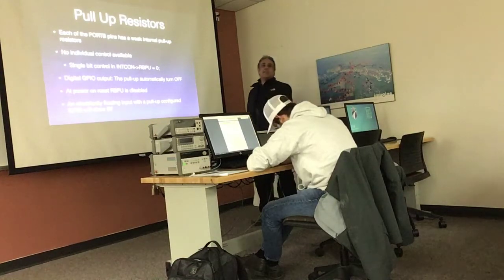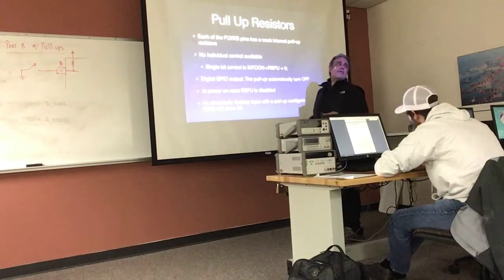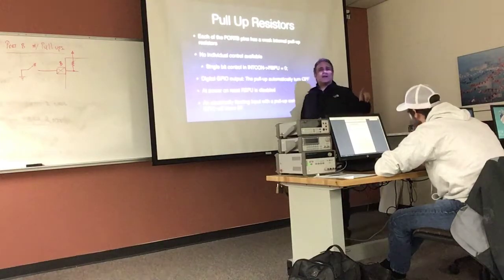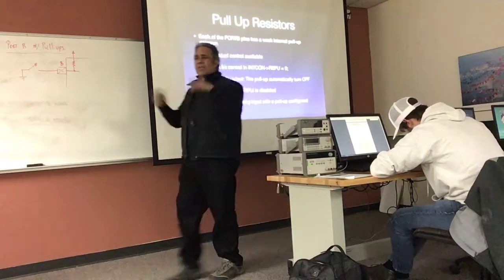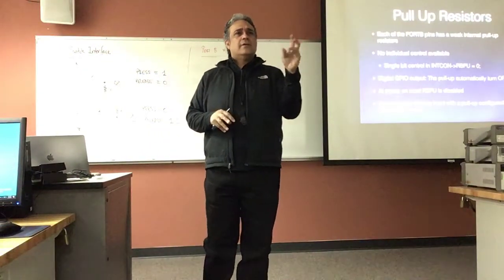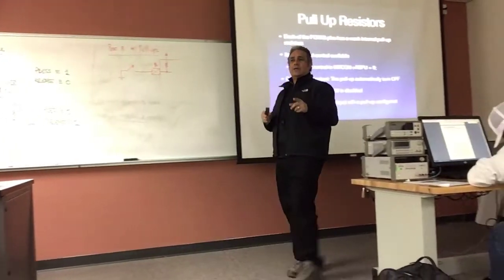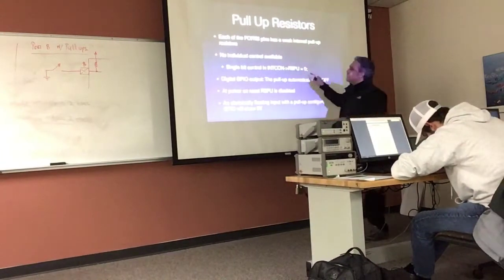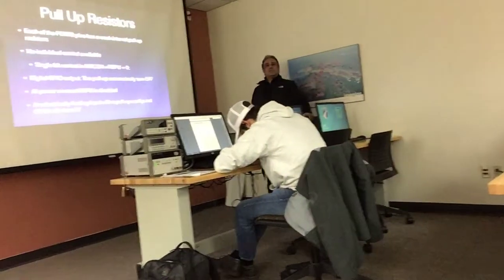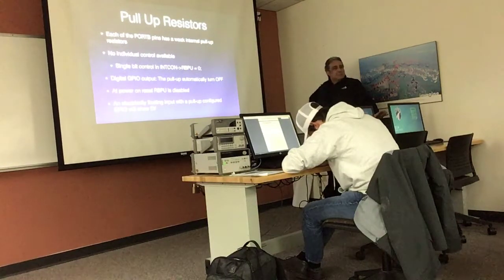The other part is that the moment, let's say that you engage the pull-up resistors, and then you make one of the pins an output. This is a great question for an exam, by the way. This is always a great question for a test. It's actually right there in the data sheet, but we don't like to read it sometimes. So here's the deal. If you make the pin an output and at the same time you have pull-up resistors, the pull-up resistor gets disengaged. It actually gets turned off. So even though there is no individual pull-up control, in some sense there is.